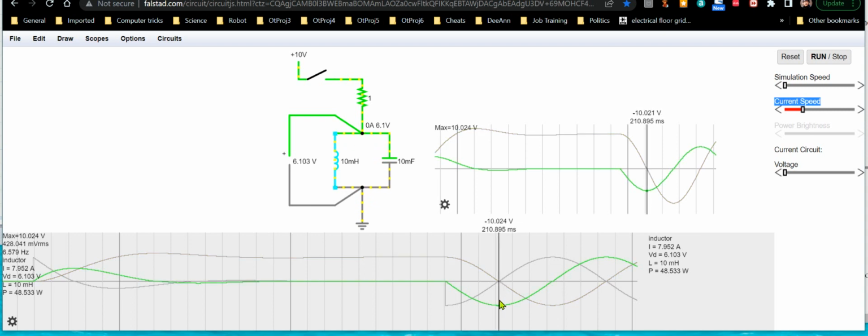You can think of it like the field was continuous all the time, even though technically it's kind of flipped. Technically the inductor doesn't generate a voltage field anymore now that it's out of energy, but given the capacitor's got all the energy, it's applying its voltage across the inductor, which is causing the inductor to counter that with its own voltage.